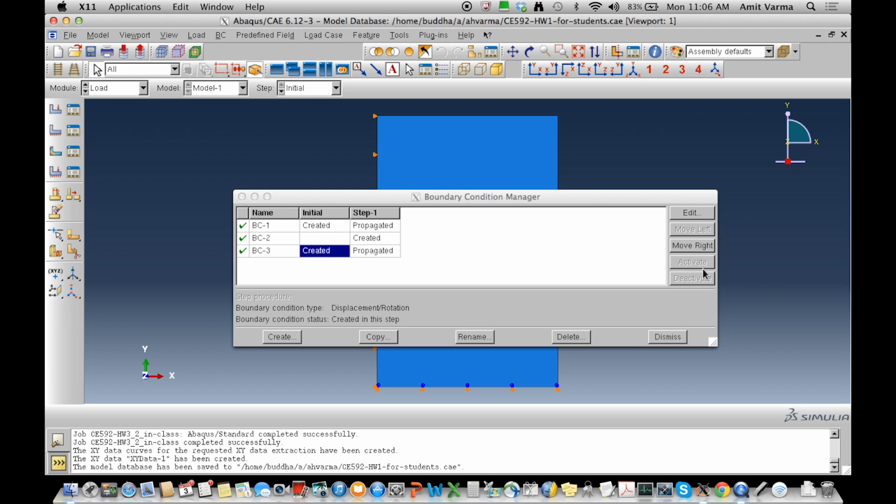Which means that when I subject it to a displacement increment of 0.01, it should work out because I've got adequate boundary conditions. Which means that my second step, when I applied the loading, I need to edit that. Can I edit that to include the U1 along the vertical edge? Probably not.